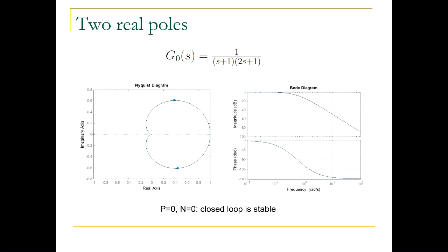What happens if I scale this by a very large K, like K times G0, right? Well, this plot would start looking like this. But it would never, ever cross the point because it does not intersect the negative real axis. This thing converges to zero, but it never intersects the negative real axis. So you will have stability for a large K.